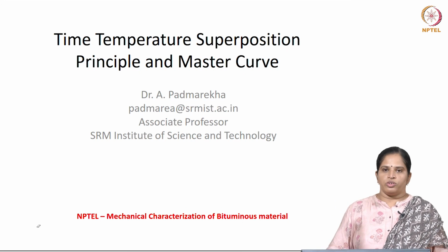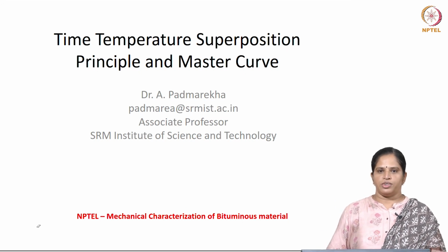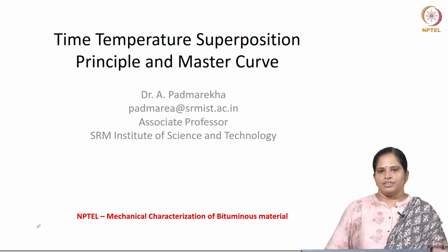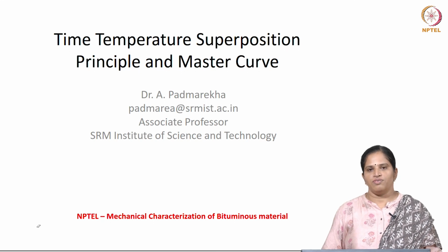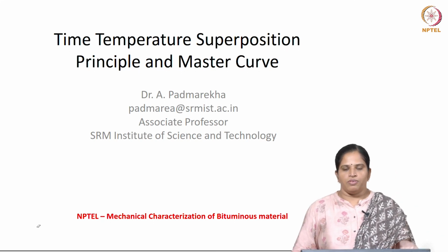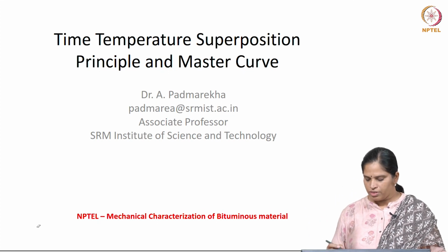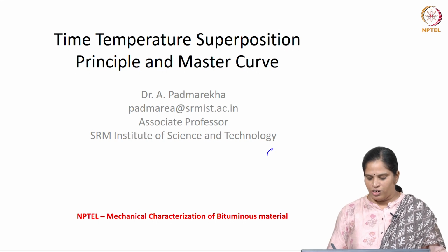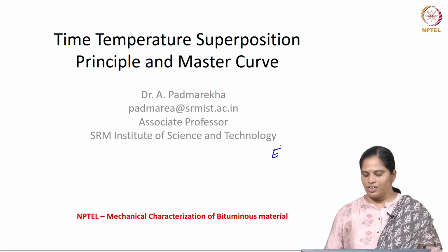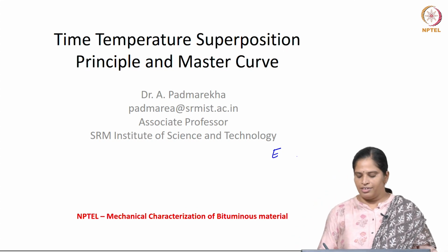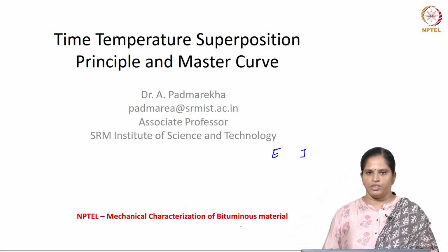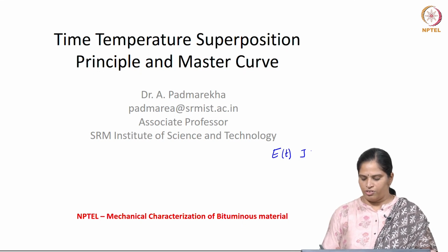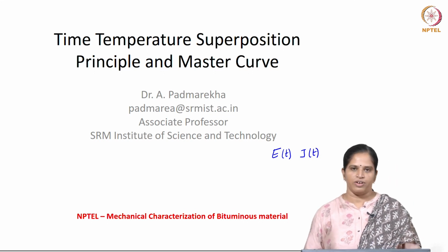Everybody. So far you have learnt viscoelastic characterization behavior in a strain control mode and a stress control mode test, and in a time sweep testing and in the frequency sweep testing mode. You have also been introduced to material functions such as relaxation modulus, which was denoted as E, and creep compliance functions denoted as J, and you know that these functions are time dependent functions and it all depends on the time factor.